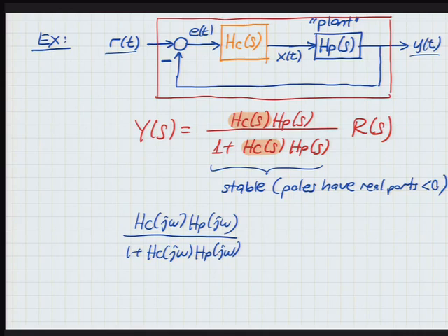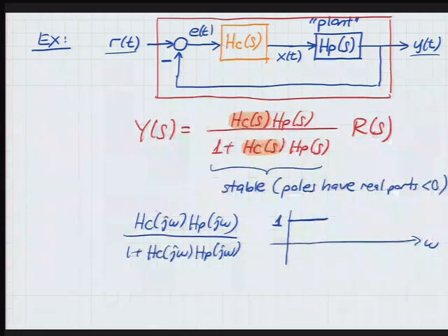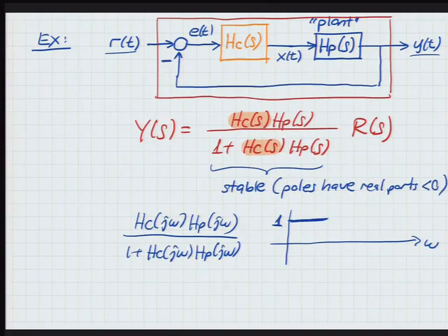And being in the ROC means that the Fourier transform exists, right? So this is actually a well-defined frequency response. So ideally, we would design this in a way that it's as flat as possible if our goal is really tracking. Okay, so you want it to look 1 for as long as possible. Why? Because I want my Y to look like R, right?